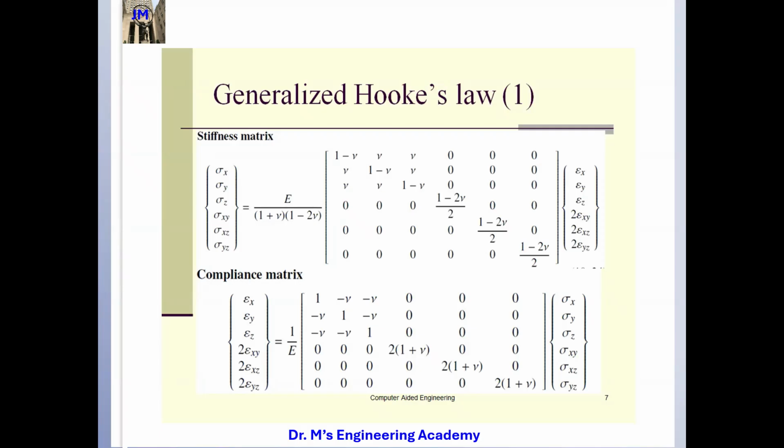We have 2 equations. These 2 equations are based on the same thing, but which equation you use depends upon what you know and what you are solving for. For example, for this one, if you know the strain components and you want to calculate the corresponding stress components, you use this equation.